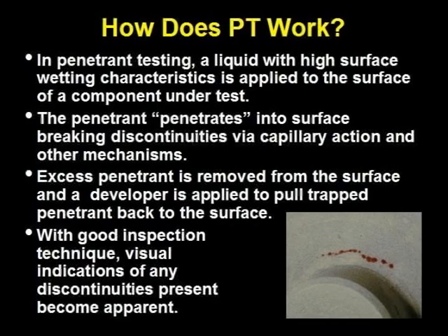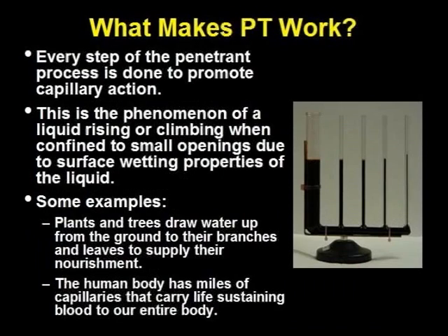The basic idea of penetrant testing is to use a liquid which is drawn into surface breaking discontinuities by capillary action. The excess liquid is then removed from the surface and methods applied to enhance the visibility of the trapped penetrant. This slide illustrates the effect of capillary action.